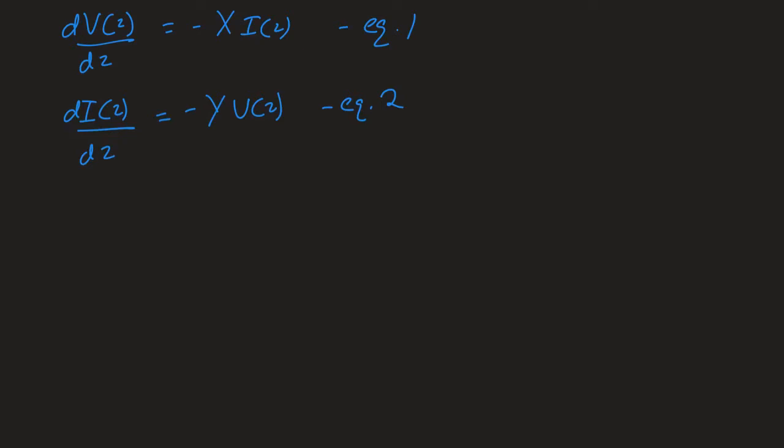These equations are in phasor form, of course, so you solve the phasor form and multiply by e to the power i omega t to get the time dependence. This X was a lumped parameter equal to i omega L plus R, and Y was equal to i omega C plus G.